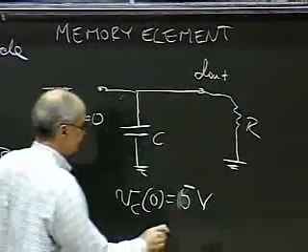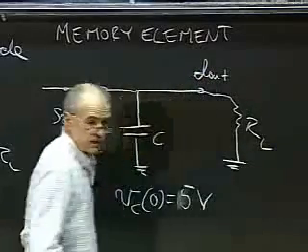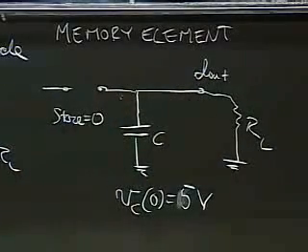And I'm asking myself, how long will this cell hold the value? Okay? And in fact, that's actually what happens in a dynamic RAM. The value on the capacitor is not stored forever. In fact, that's why we call it dynamic, because we have to come back and restore it every once in a while. Okay? So for how long are we going to store the charge?